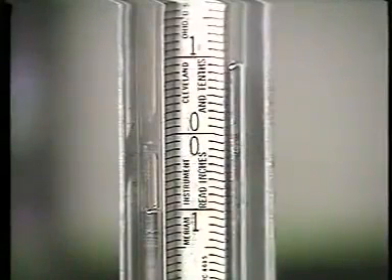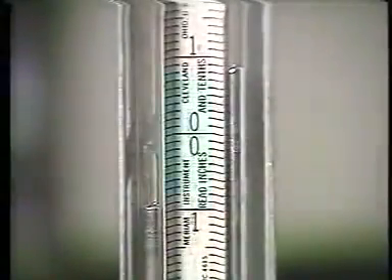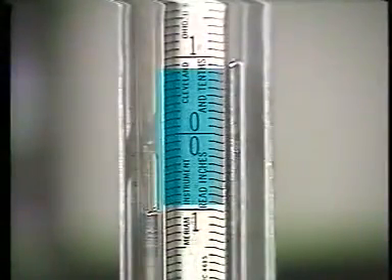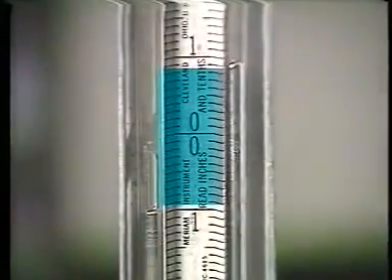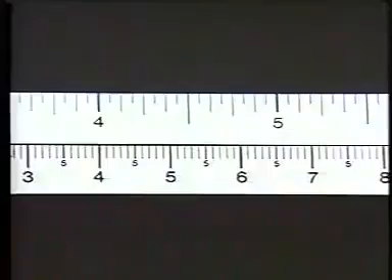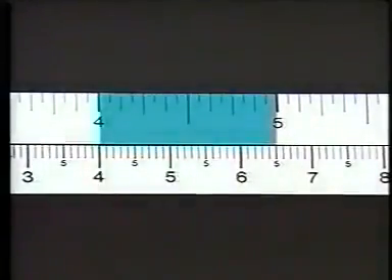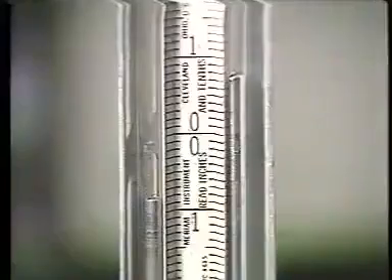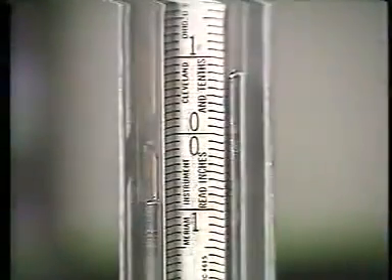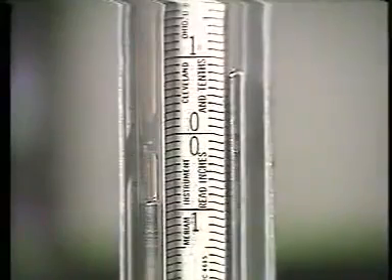The pressure of the gas forces the mercury down in the left leg and at the same time up in the right leg. We can get a measurement of the gas pressure by finding the difference between the levels of mercury. This can be measured in units that measure distance, inches or millimeters. This distance represents the height of the column of mercury that the pressure can support.